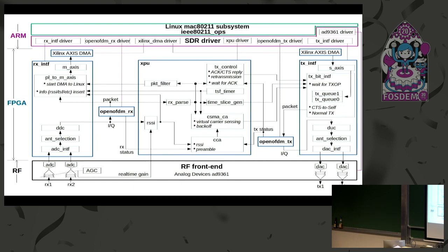Okay, above the FPGA, those are driver modules. The AD driver communicates with the front end directly to do the channel tuning, right? TX, RX stuff. And the TX interface driver configures the DMA driver, the Xilinx DMA driver. We modified the Xilinx DMA driver, tailored for this case. And the TX/RX driver, DMA driver. Basically, those drivers configure the FPGA registers, functional registers, to control the behavior of your FPGA design.